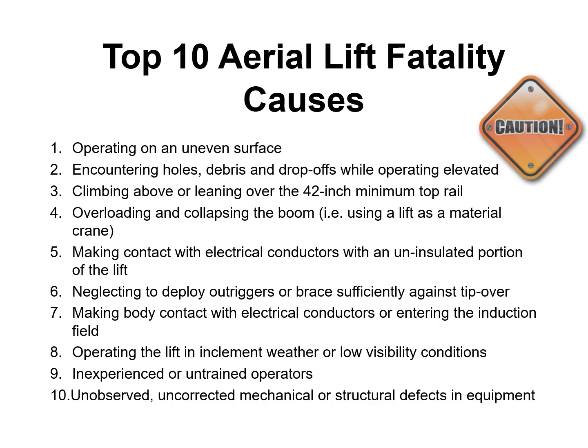Top 10 aerial lift fatality causes. Operating on uneven surface. Encountering holes, debris, and drop-offs while operating elevated. Climbing above or leaning over the 42-inch minimum top rail. Overloading and collapsing the boom, i.e., using a lift as a material crane.